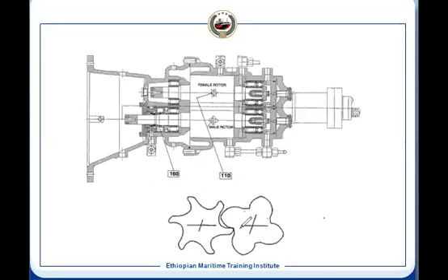And this is the compressor. You can see this is the screw compressor. If we use a screw compressor, it is like this. And then, as I told you, as it moves the fluid, the volume is reducing. The design is made in such a way that the pressure keeps on increasing. Volume is reducing. The same mass of refrigerant is getting compressed. So the pressure is increased. That means the density will increase, so mass flow rate will increase.